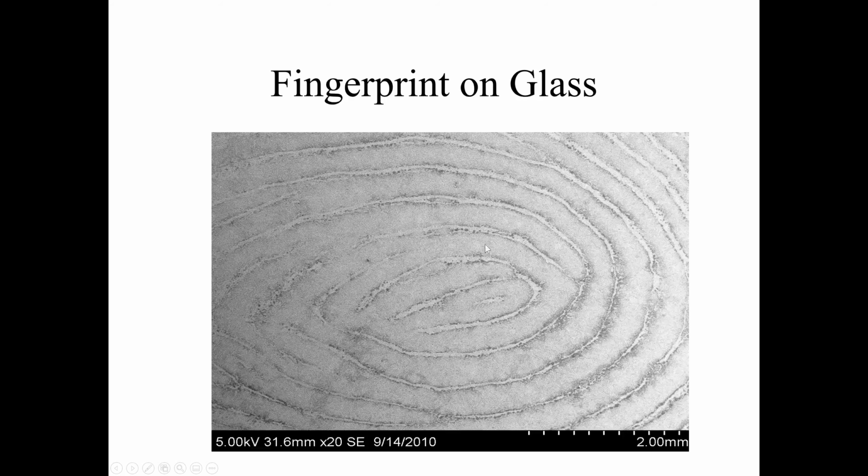You can see some carbon contamination. Basically, when you touch the slide, you're inputting a biofilm of your skin oil. Then when you coat that, that's what it's imaging. No luck with the backscatter because the slide is all lightweight elements, and the oils on my finger are lightweight elements, so pretty much this whole image is going to come out gray. The secondary emission mode is good for this.